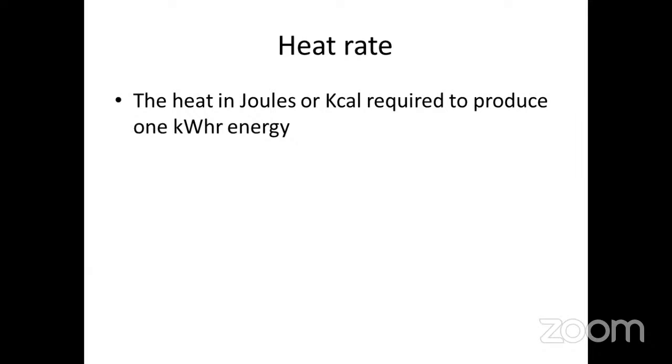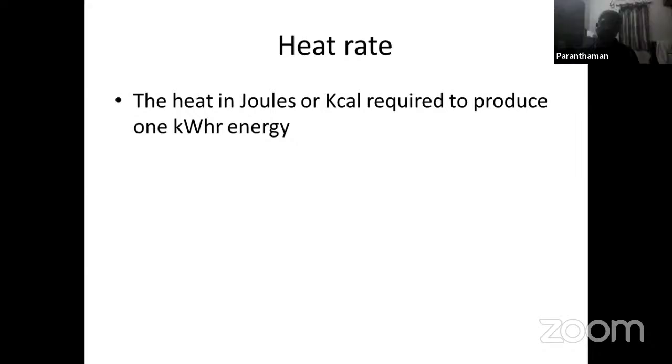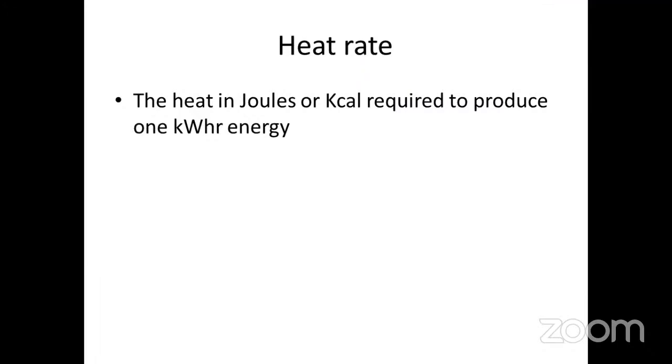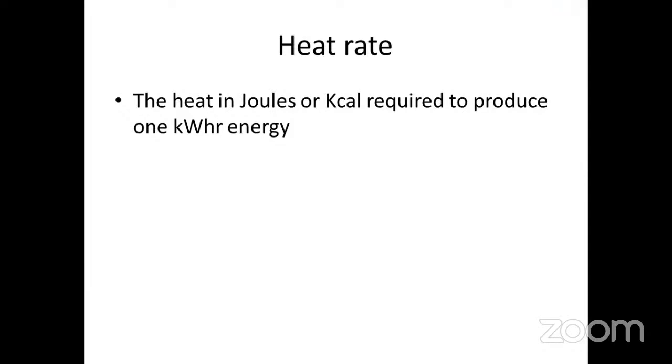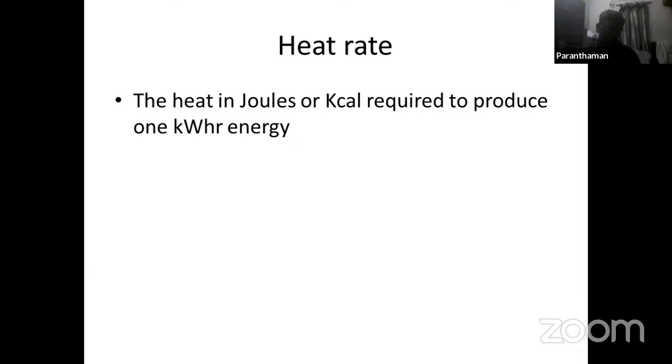I square R is okay. For resistance, you have to consider the resistance of the conductor. So there comes the area of cross section. If you go for higher voltage, the area of cross section is very limited, less. The resistivity of the conductor is less. So the transmission loss will be less. The I square R loss will be less.